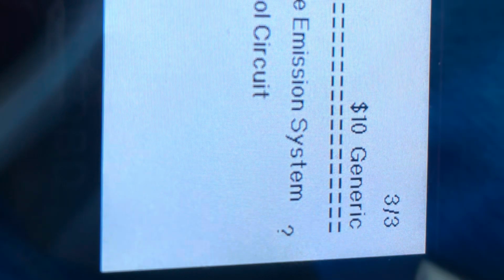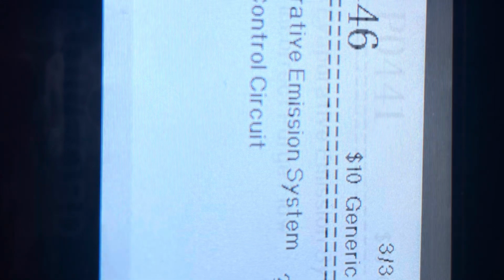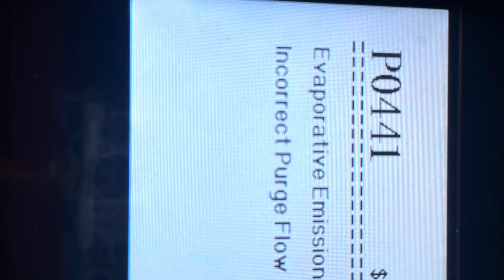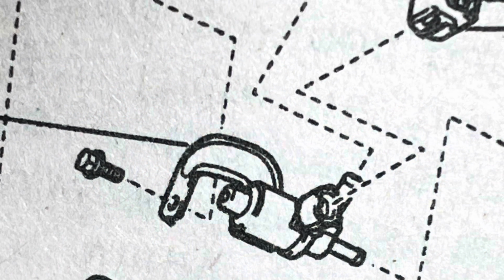So during the troubleshooting, I managed to trip a few more codes. One of them is the incorrect purge flow, which I had unplugged for quite a bit. I've been running these evap tests, so maybe that one's nothing. But also just a generic evap code. So those are all to be expected. All have now been reset.